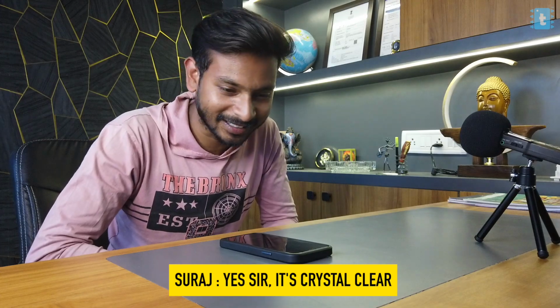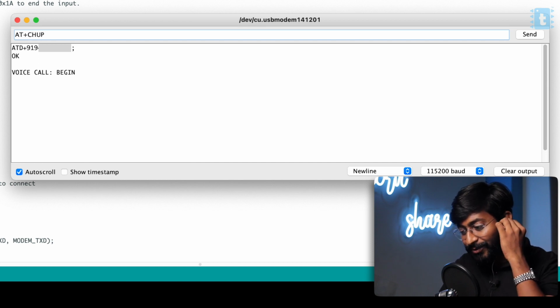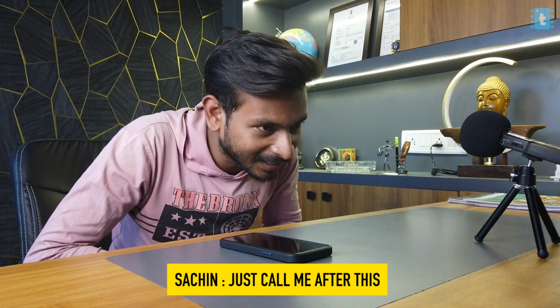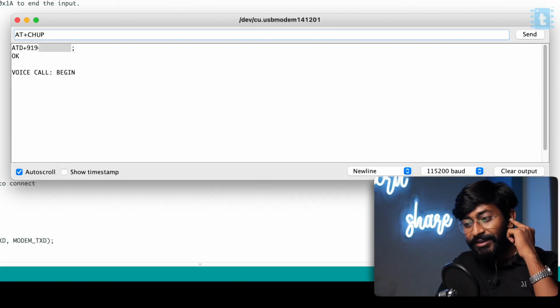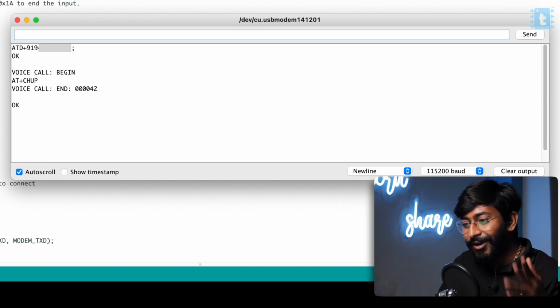Great. So now to hang the call, we have a command called AT plus CHUP. Now this will hang the call. Okay, so I'll hang the call with the help of this command, and yeah, the call ended. And now let's just wait for him to call me back, and let's see how to receive the call on this.